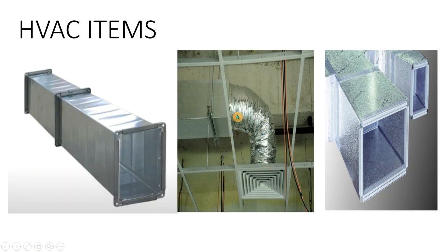The length of this duct will be from 1.2 meters to a maximum of 3 meters. Above that, you will not use this. Majorly, this duct is useful only for the connection from the main duct or main branch to the diffuser or the grills. So these kinds of items will have the flexible duct. Again, I'm repeating, the length shall be 1.2 meters to 3 meters.